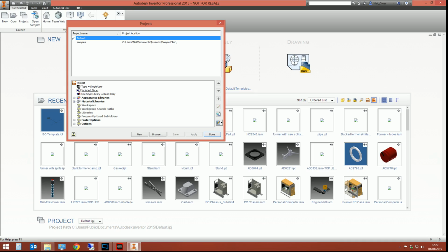Your top level assembly needs to know where they are, and you can't realistically expect Inventor to search your entire PC, or if you're in an office, the entire server or network to locate a file. So the project file gives Inventor this little umbrella region, this little folder structure. And it says, right, when I open up this assembly, all my files are going to be underneath here. And that is your workspace area, right? That's the bones of what a project is and what it's for.